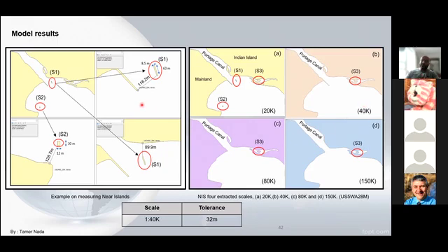By calculating those islands' distance from the mainland by means of the Near Distance tool in ArcGIS, I can calculate the distance for all islands from the mainland and sort them in a table. So I figured out that those two islands are more than the tolerance for this scale.